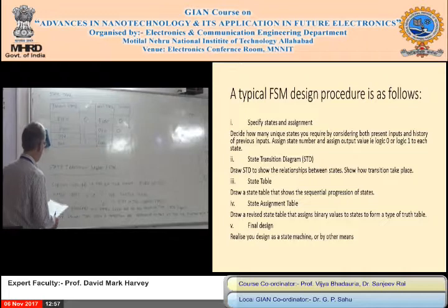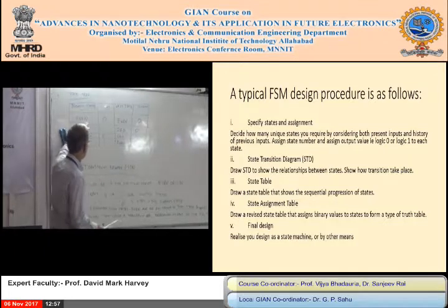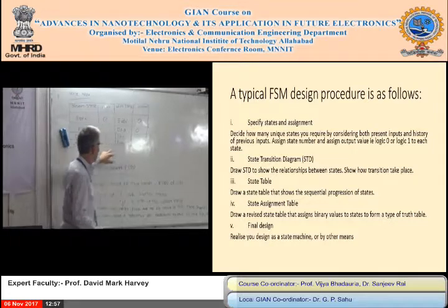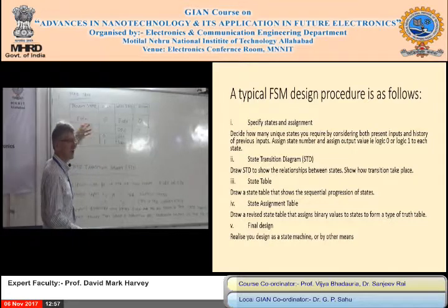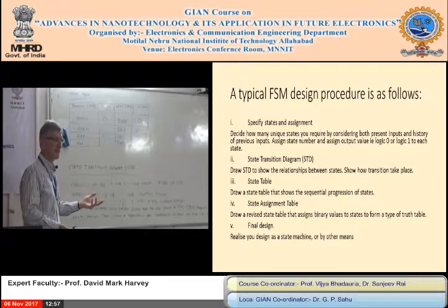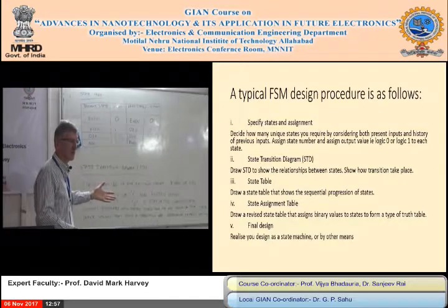So I made the decision, whether it's right or wrong. It doesn't matter, it's the engineer's decision. Even has an output of naught, so I'm going to make even naught. Odd has an output of 1, I'm going to make odd 1 in my design. Could have chosen the other way. The difference probably being you might need 1 extra inverter in the design. So you could try both ways if you've got time. If we're working in the design industry, try both ways, it won't take long.